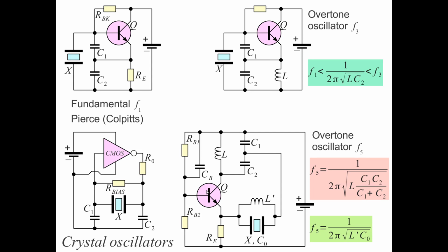We have an oscillator circuit built with a filter. This filter is made by this tuned circuit here with a resistor and two capacitors. This is just a voltage divider built with two capacitors, and a crystal connected in series. So the frequency is roughly defined by these tuned circuits, and then there is the fine tuning of the frequency with the crystal. In order to improve the performance of the crystal, we can compensate its parallel capacitance with a parallel inductor to the crystal.